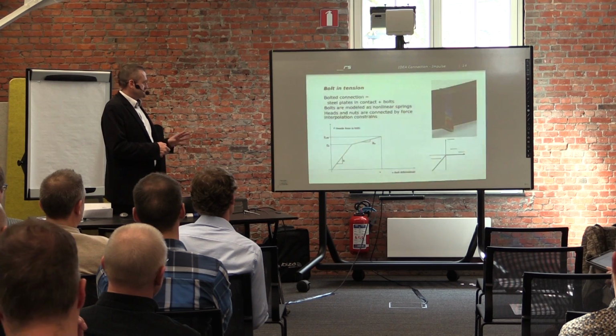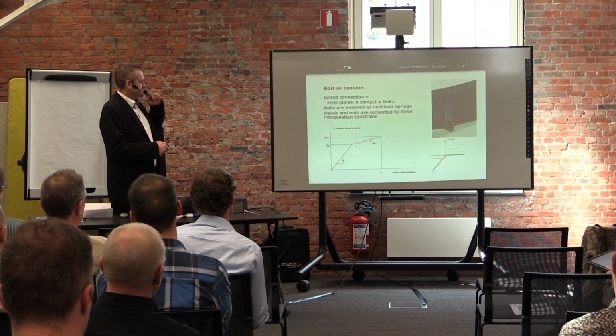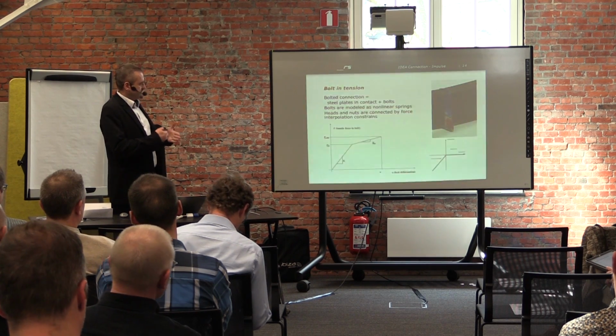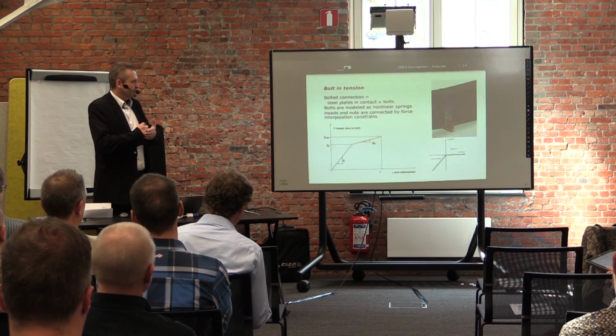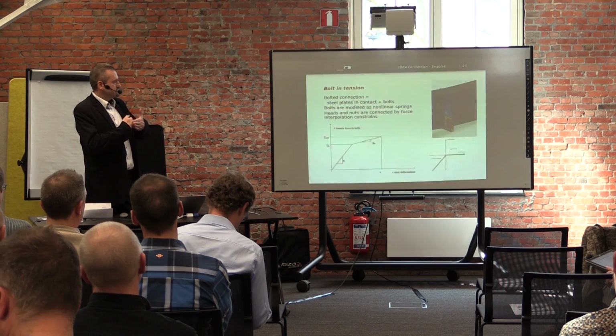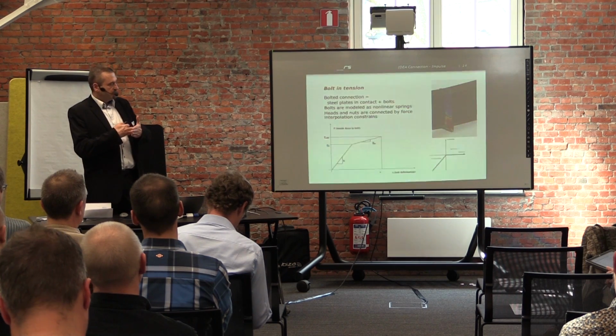We speak about bolts. In fact, a bolted connection is no rocket science. It is two plates and several bolts. It's nothing special. But the analysis model needs some things. So at first we must be able to analyze this contact between two plates. And the plates in contact can work only in pressure, but not in tension.